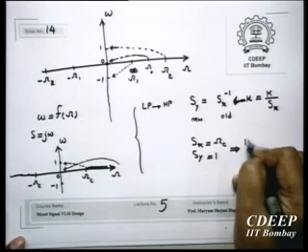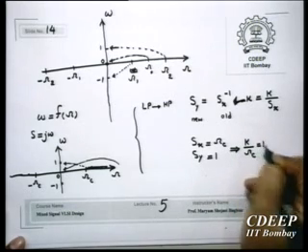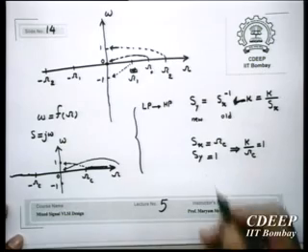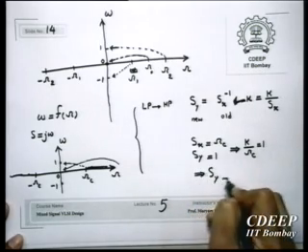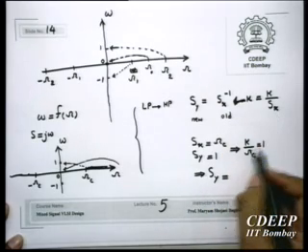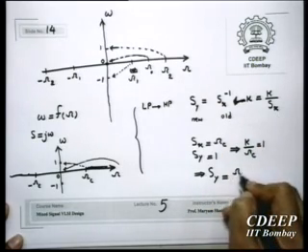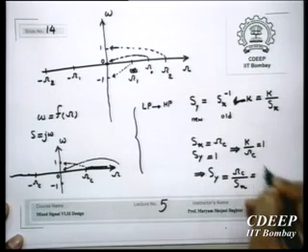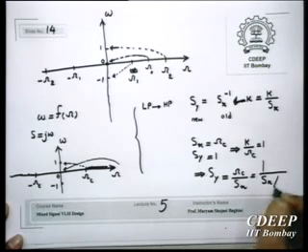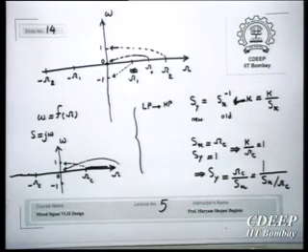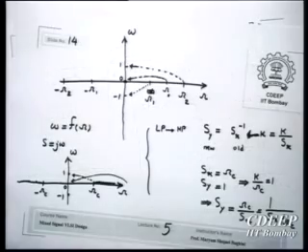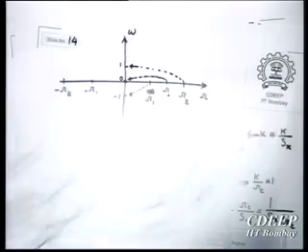This means that k upon omega c equals 1, in other words k is equal to omega c. Therefore, Sy is equal to omega c upon Sx, or you can write it in this manner, which is more meaningful: you normalize Sx to omega c, and reverse it. So this is very easy to convert low pass to high pass. For example, in this example, the multi-feedback filter was a low pass filter.